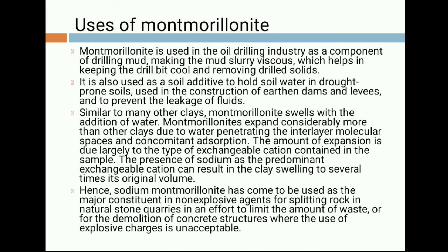That is the place where using explosive is banned, or the places where we cannot use explosives. In that condition, we can use Montmorillonite replaced by sodium, which is called sodium Montmorillonite, to break such rocks. Or for the demolition of concrete structures where the use of explosive charges is unacceptable, we can use sodium Montmorillonite.